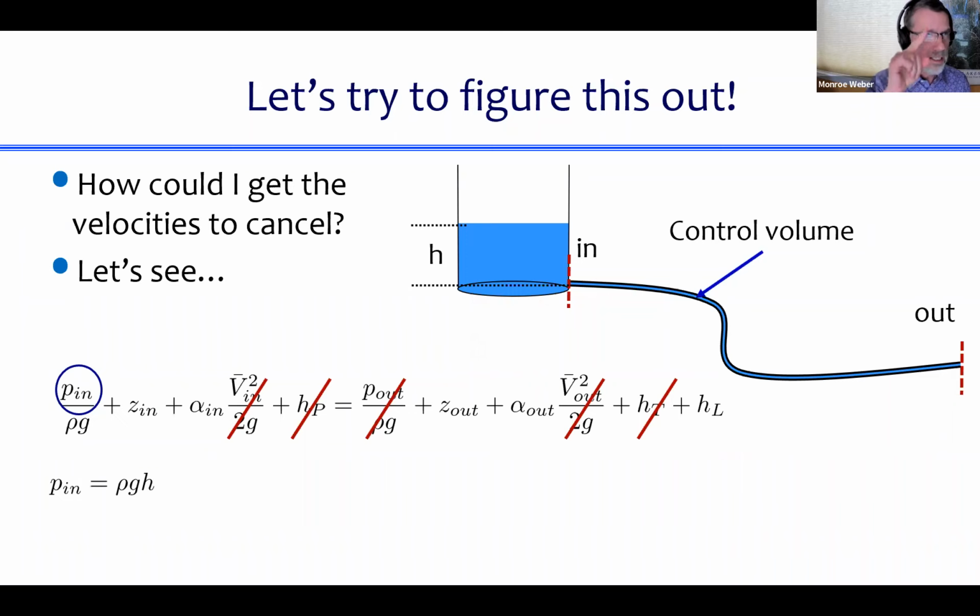The water is accelerating as it's going through that control surface. It's got some velocity, and that means that this isn't a statics problem. So we can't use rho GH, I'm sorry to report, to calculate the pressure at the control surface. You see how that problem evolved?